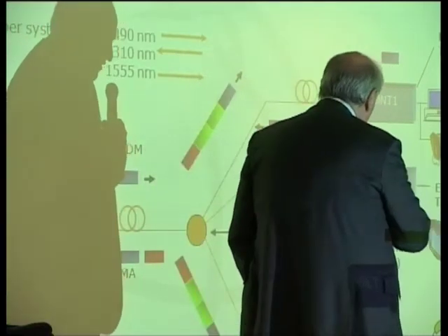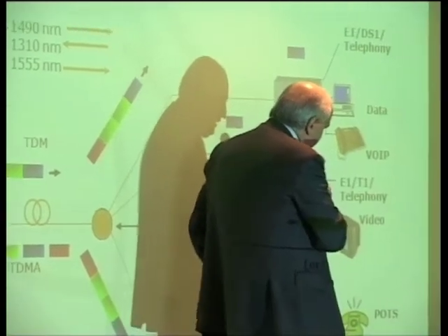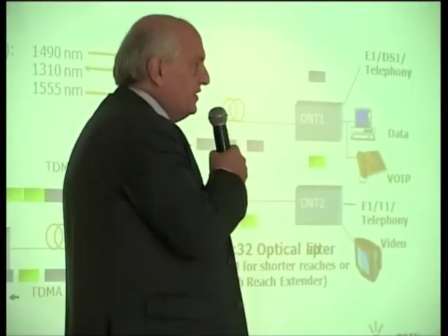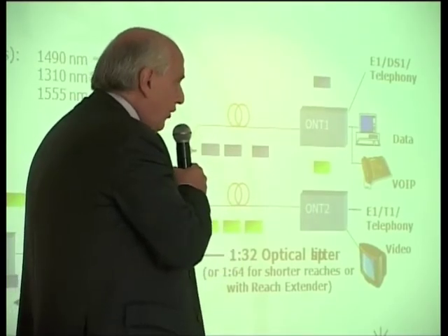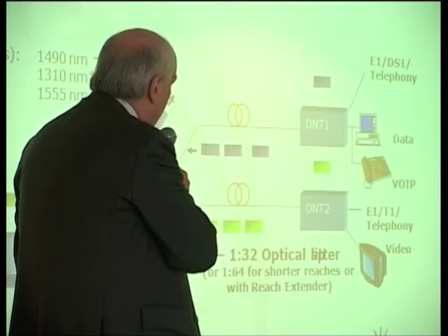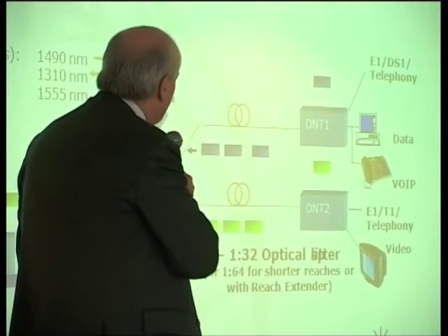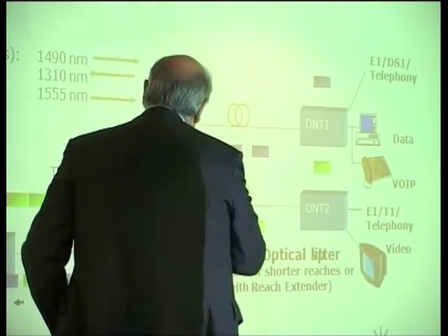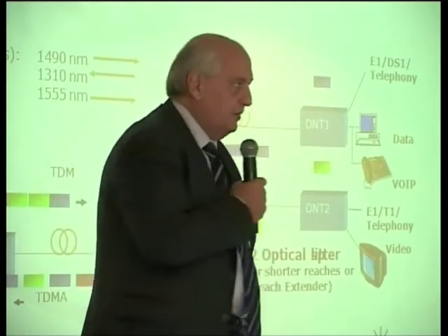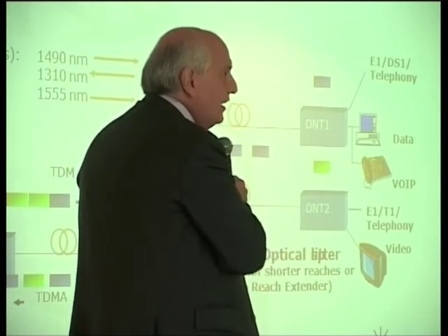The other important thing we saw yesterday is that since the various network terminations are at different distances from the optical line terminal, some ranging procedure is to be foreseen in order to have the distribution to any of the ONT of the timing information, which means the phase according to which they must transmit their packets. And moreover, since the difference in the path length can be as high as 20 kilometers, also the power which is sent into the network by each ONT should be reduced or increased according to the distance.